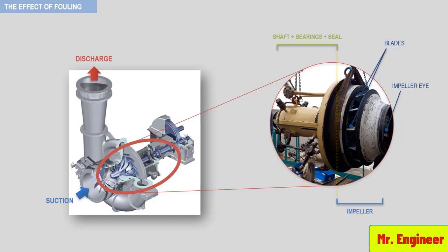So what was the root cause? Well, after an exhaustive troubleshooting period, it was discovered that one of the filters upstream of the compressor was not performing its duty, and the polyethylene fines were not entirely retained and were carried over to the compressor section along with hydrocarbons. Redesign of the filters solved the problem.